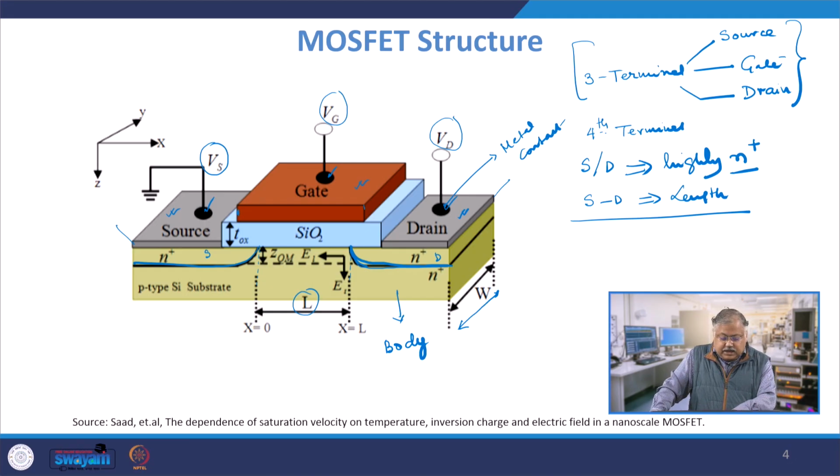Assuming that they are matching here, if this is the source and this is the drain, then you will see this is the oxide layer, and then you have this metal layer coming here, and the semiconductor. That is the reason it is a metal oxide semiconductor. This is N plus, this is N plus, this is metal and this is the oxide layer. Now, you see they are perfectly aligned with respect to each other in the source drain region here as well as here. Here you have some overlap.